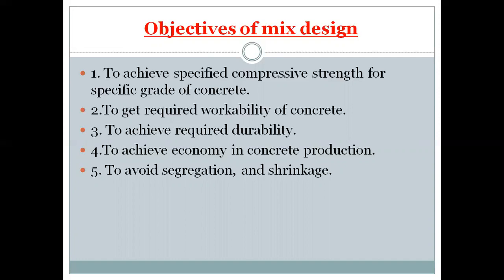The concept of the mix design is deciding the proportion, that is one part of cement, two parts of fine aggregate and four parts of coarse aggregate, and also the water cement ratio. To achieve the specific grade of the concrete, we have to design this proportion, and for this we require the process of mix design to achieve the required grade or the required compressive strength.